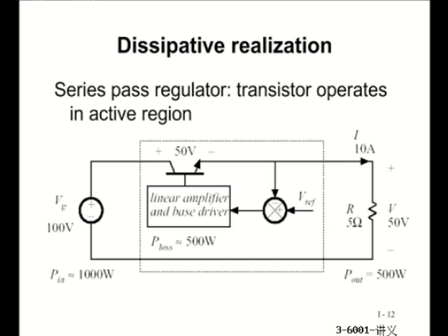So therefore, through this negative feedback control, we are able to handle disturbance coming from the load, if the load resistor is changed, or disturbance coming from the voltage, from whatever disturbance source, we can handle that. Through this automatic feedback control, we are able to control the output voltage at a specific value. And this really was implemented in engineering.